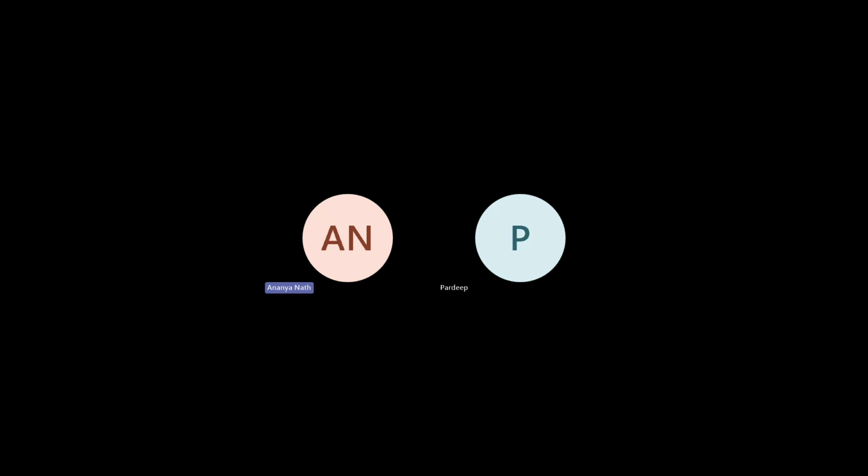Under this state of the art, we have different processes like WAAM, wire arc additive manufacturing, powder DED, wire DED, then laser DED, plasma DED, arc DED, wire and powder DED both mixed together, and hybrid DED. So these are variant processes under the state of the art of DED, directed energy deposition. Like that, for the other six categories also, we have different processes. So I have a PPT for that.